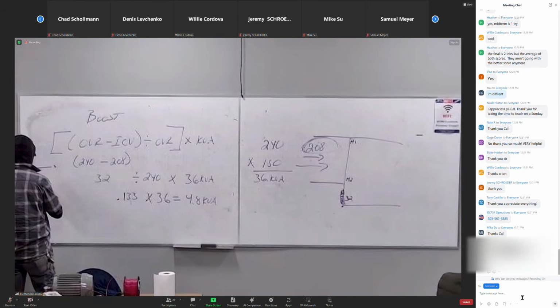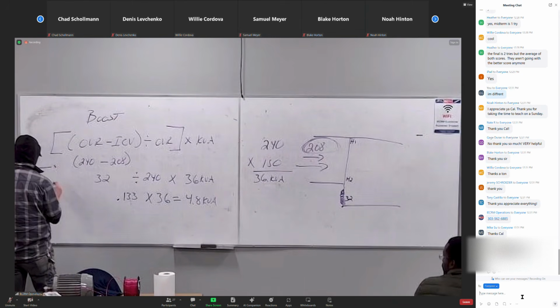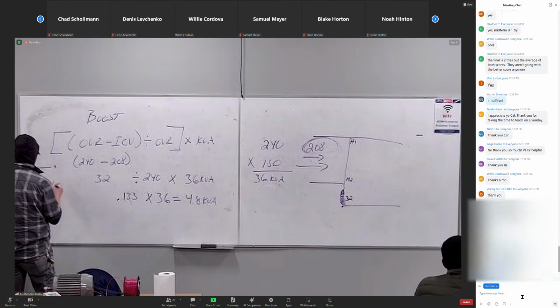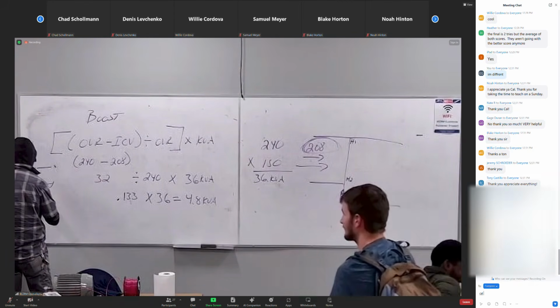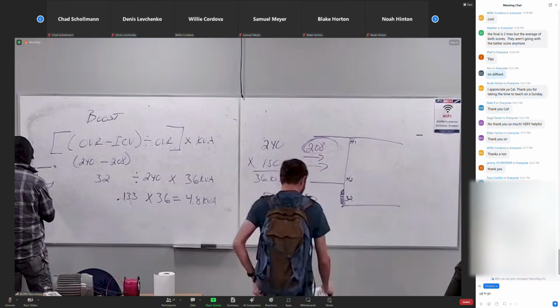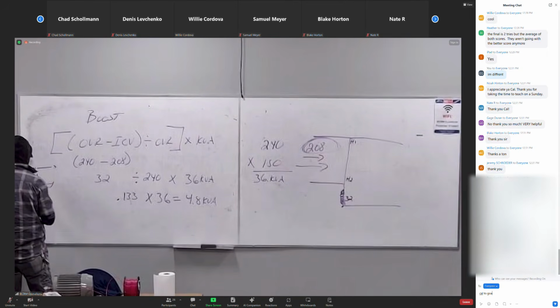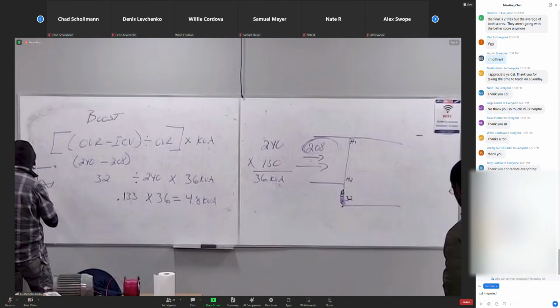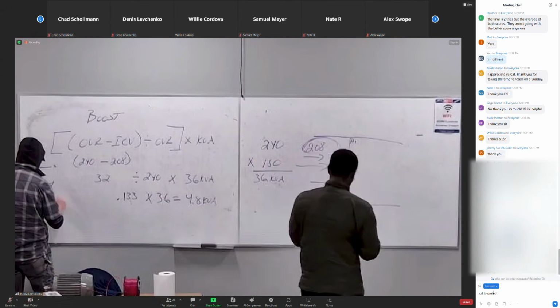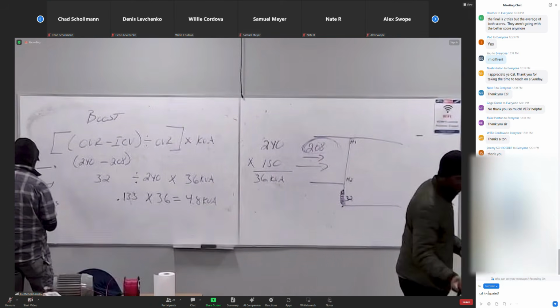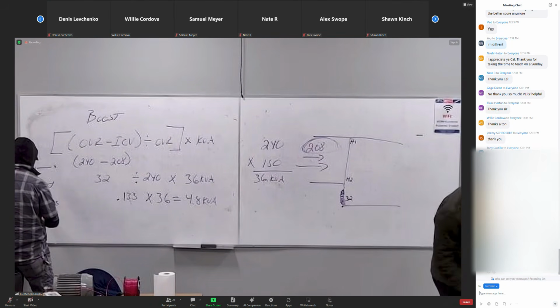Yeah, this is how we got this answer, because it's 3 phase. So it's just Ohm's law. This number here is this in parentheses. So do your voltage first and get your 831. Now solve for your current. 112,500 divided by 831.